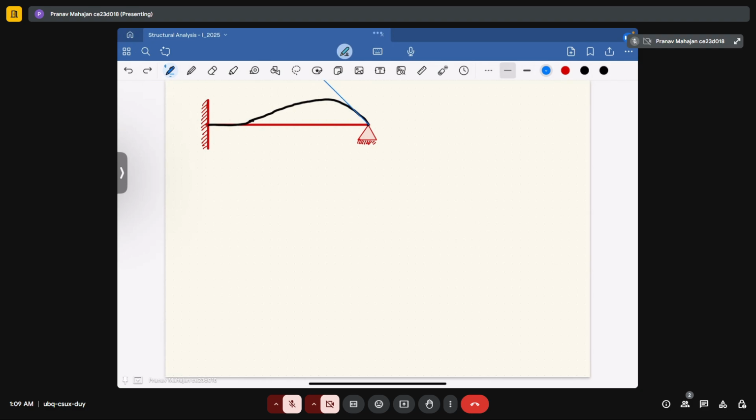okay, so this theta will be equal to 1, and if this theta is coming, that means 4 EI upon L will come into picture because of the free end, and its carryover moment will be equal to 2 EI upon L. Now since they are providing clockwise moment, an anti-clockwise shear couple will act.